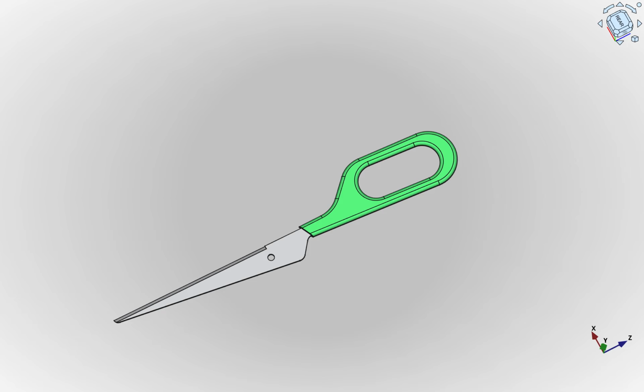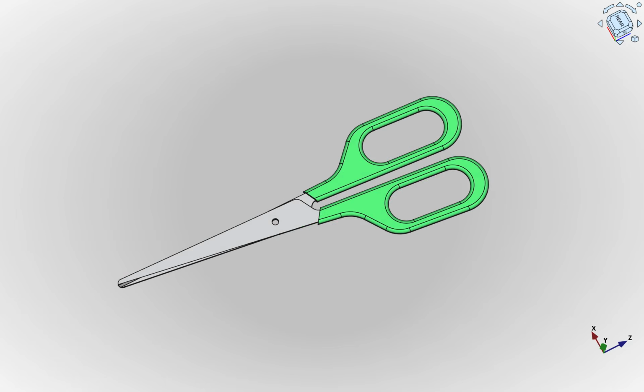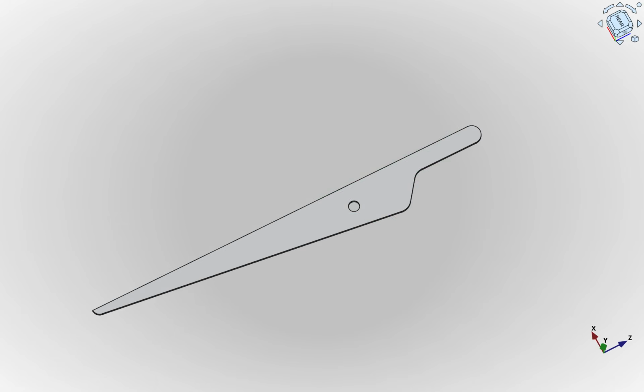Now we just have the sub-assembly and the fastener. When we come to reassembling, we take that sub-assembly and duplicate it and bring them both together with the fastener to create our finished assembly. Each part of this assembly will be modeled separately. Additionally, each part would undergo a repeat process of simplification. For instance, the blade can be simplified as a basic extrusion for the steel, and then an edge is added using a chamfer. These two elements are features of the blade. The part design is a feature-based modeling approach.